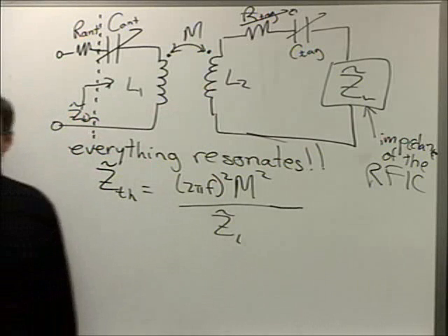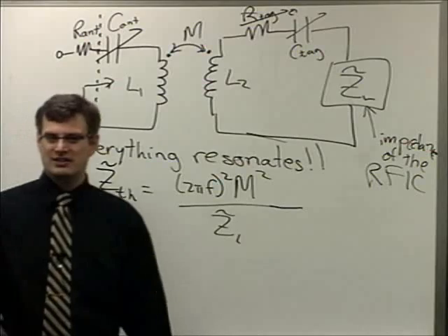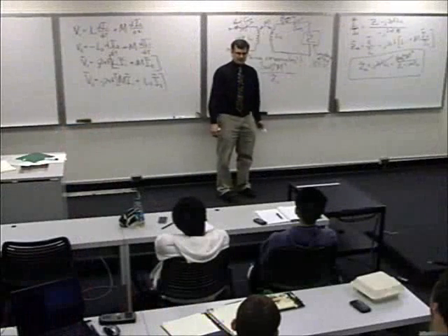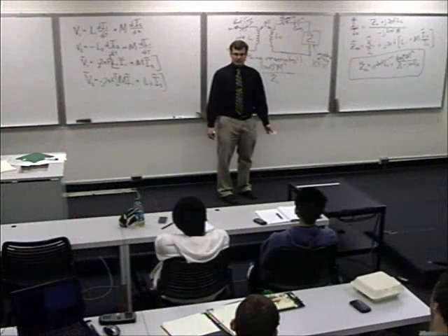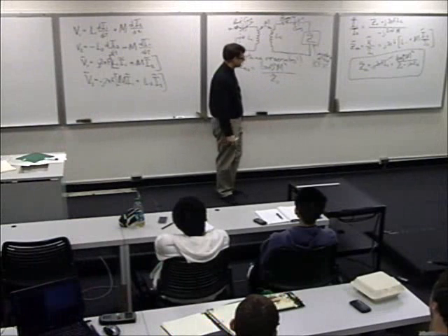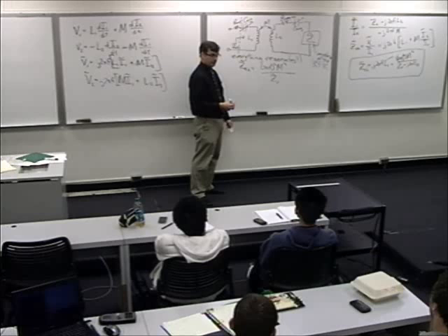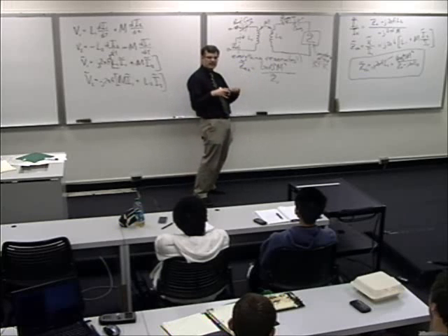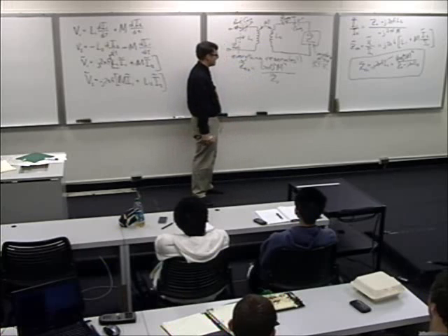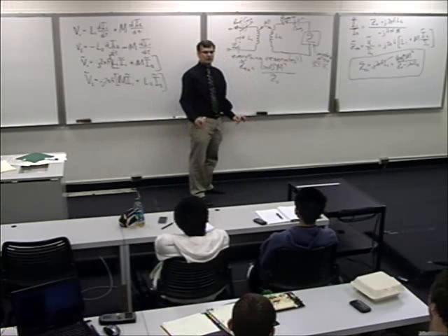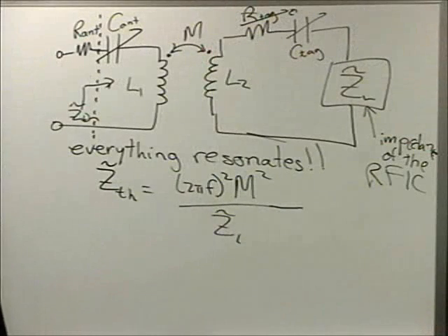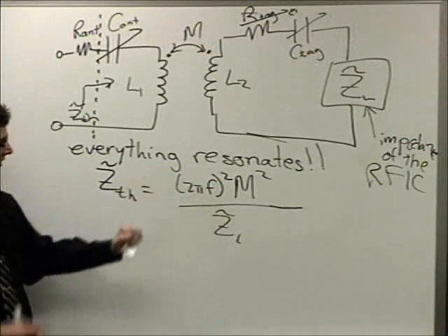There are other problems working with higher frequencies, though, because if you go too high, it starts to radiate power. Your system, at least from a coupling point of view, becomes less efficient. There are more losses. Skin depth, for example. Your traces become more lossy as the currents cling to the outside of the conductive path. So you can only go so high before you can't play this game anymore of increasing the frequency. There's a good way to couple information, though.